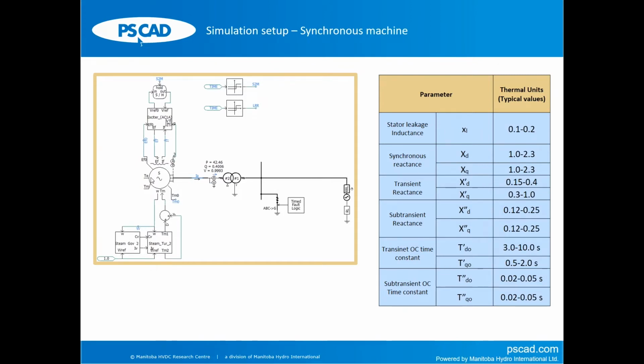They are already done. You will see now in this example, I have exciter AC1A. If your exciter is AC2B or something like that, all you do is click here and select that exciter. I will show you. So you don't have to rewire.